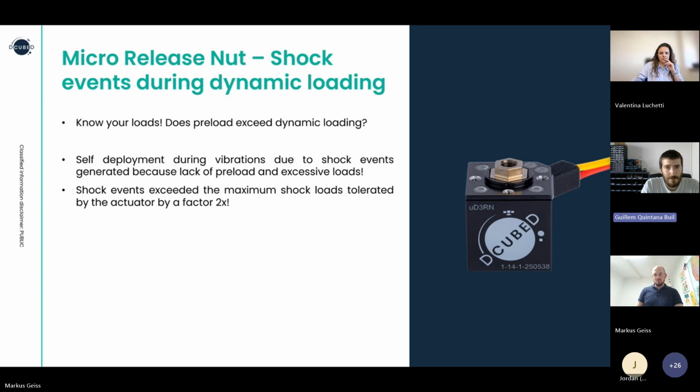But I would like to highlight a couple of elements that are super important. One is the amplification factors, and the other one is the resonance frequency of the different elements. And this can be super critical, because if the understanding of those dynamic loads is not proper and you underestimate them a lot, there's a chance that the dynamic load might be higher in magnitude than the preload that is applied.